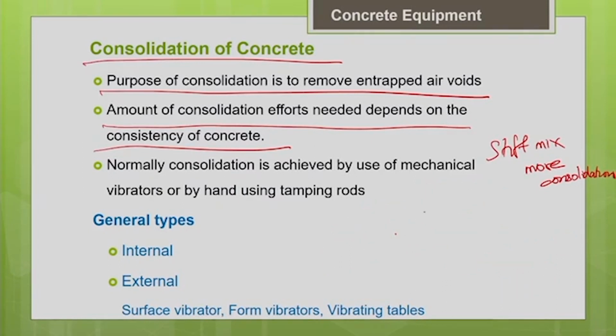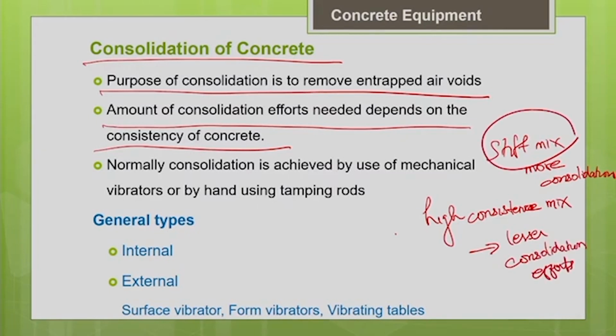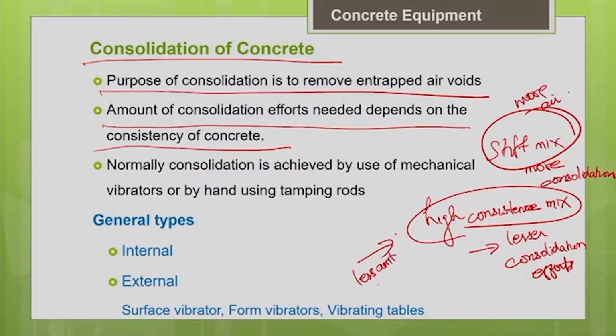For a high consistency or flowable mix, you need lesser consolidation effort. This is because in a stiff mix, more air is likely to get entrapped, while in a high consistency mix, only a small amount of air will be entrapped, because of the presence of more water in the mix. So basically, we have to match the vibrator with the concrete consistency. Depending upon your concrete consistency, you have to select the consolidation method needed.